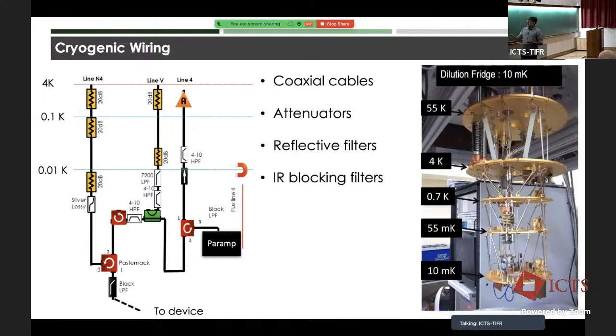These are needed in order to do two things. One is to separate the incoming wave from the reflected wave. So remember, we have to measure the scattered wave from the device. And they also help in protecting against noise coming from the wrong direction.